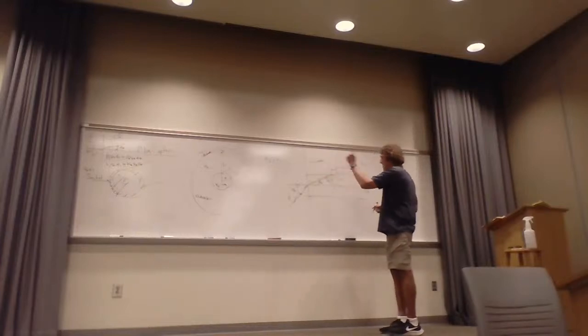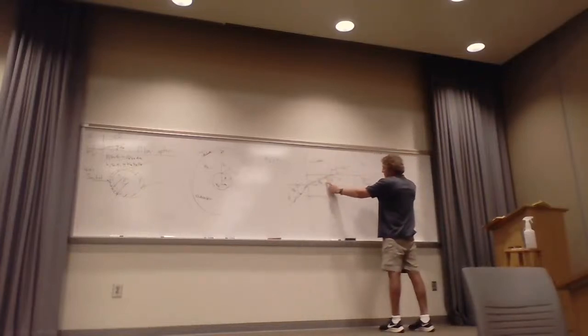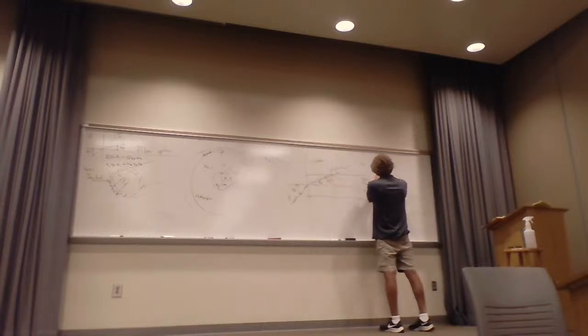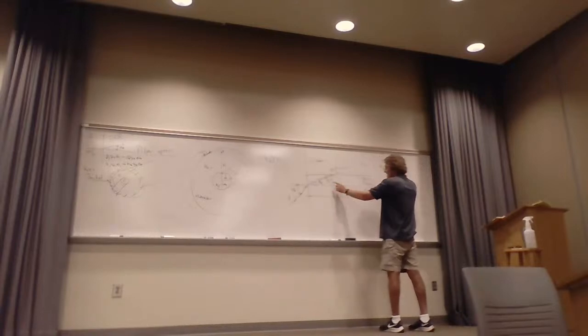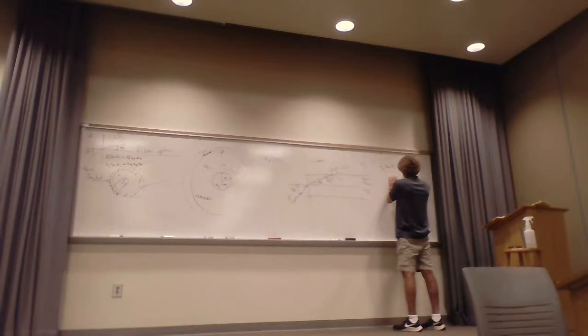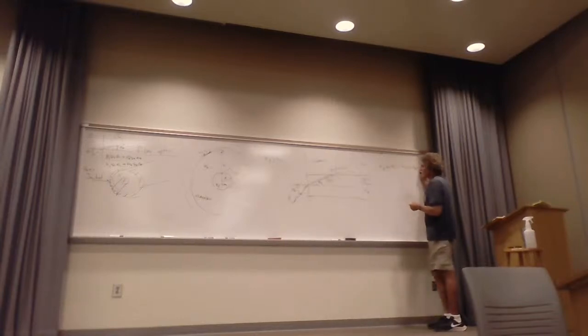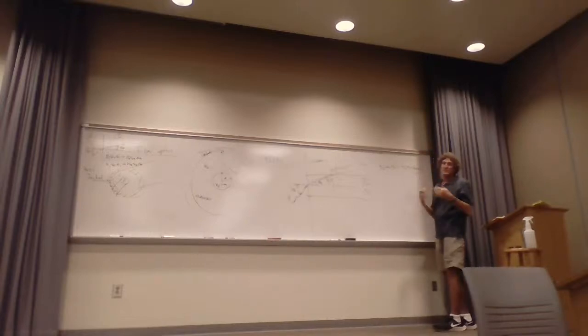Okay, so having said that, when I look at this, I have the index of refraction of the fiber, n_f, times the sine of theta c, because I'm trying to be consistent with Dr. Wentworth's book, would be equal to the index of refraction of the cladding, n_c, times the sine of the cladding angle, theta clad. Well, this is going to go to 90 degrees. What's the sine of 90?